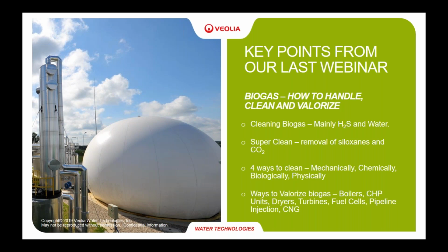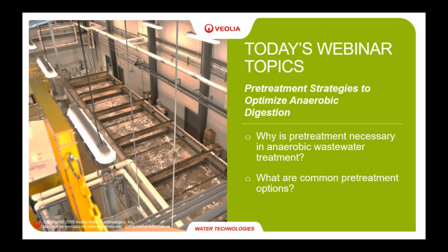The last three, the fuel cell, pipeline injection, and CNG, actually require very, very clean gas. So you need to go down to that, getting your siloxanes and CO2 out for those. So it's a bit more challenging. But if you're interested in that, again, all of our former webinars are available.